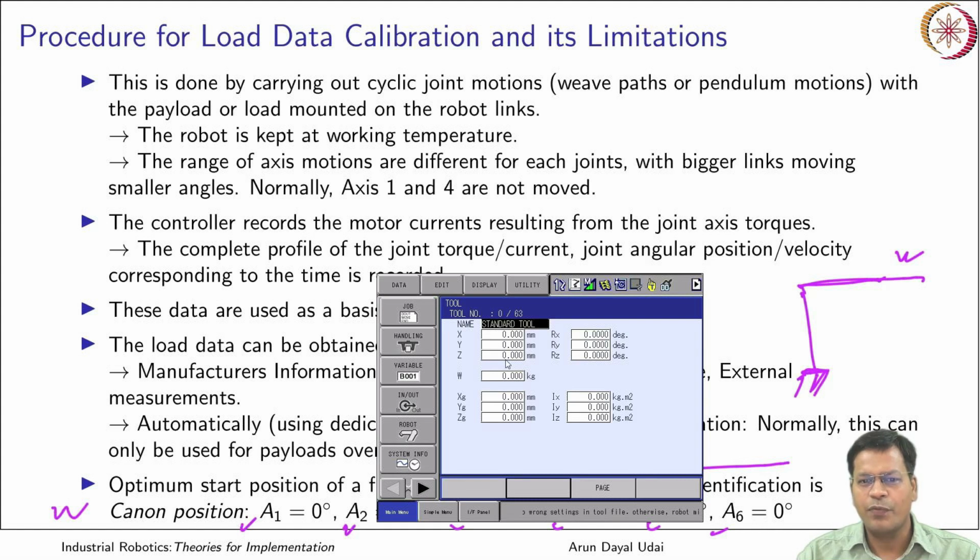That is the offset of the tool center point from the flange. So this is the data which comes from there. Okay, this is the weight of that. This is to be identified, and the location of center of gravity is to come here. This is the moment of inertia which is to be fed here. Okay, it can be done manually, but now this robot will do it through its automatic code.